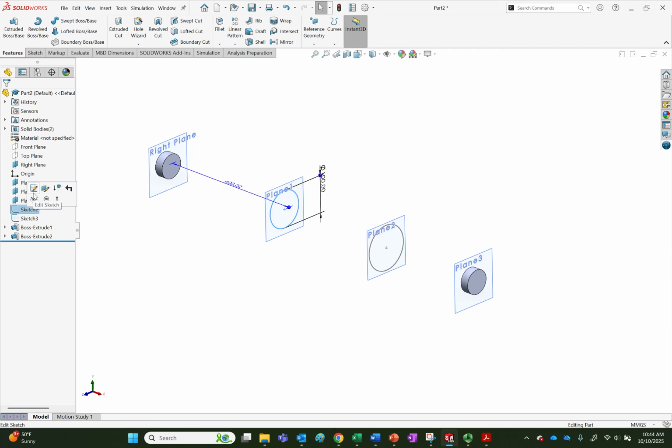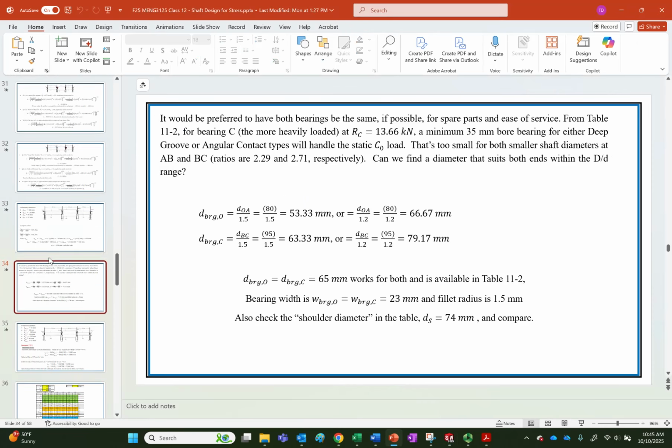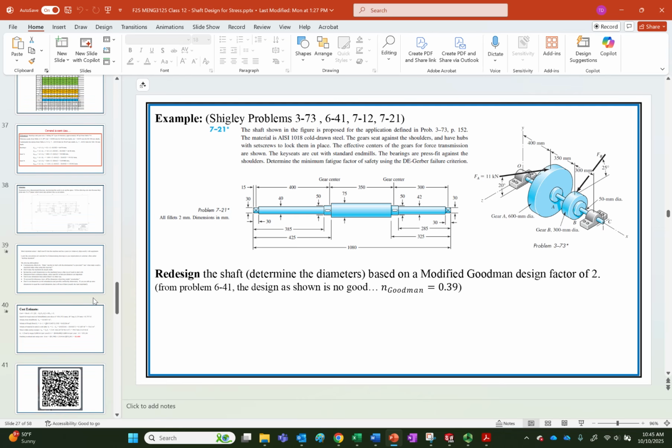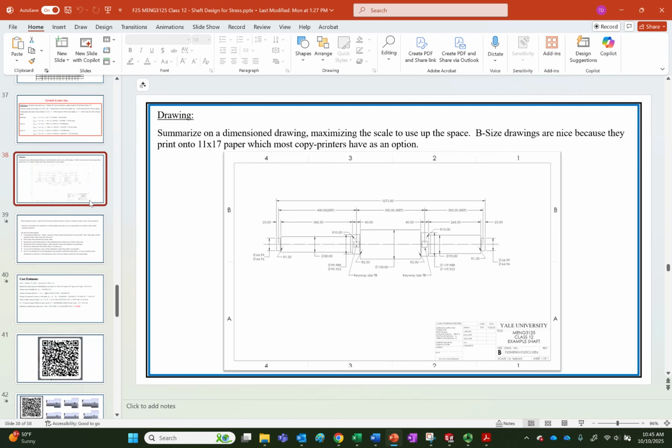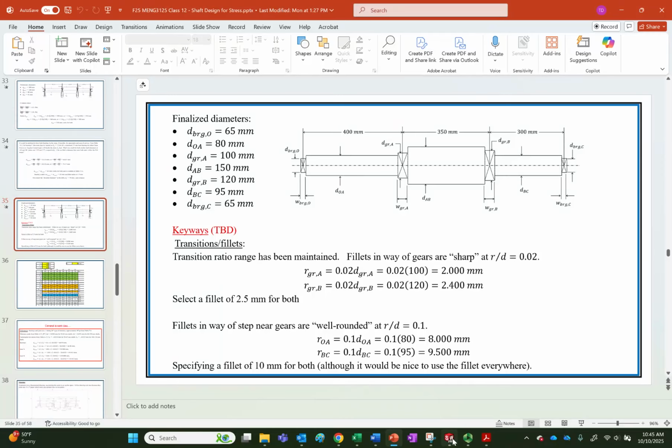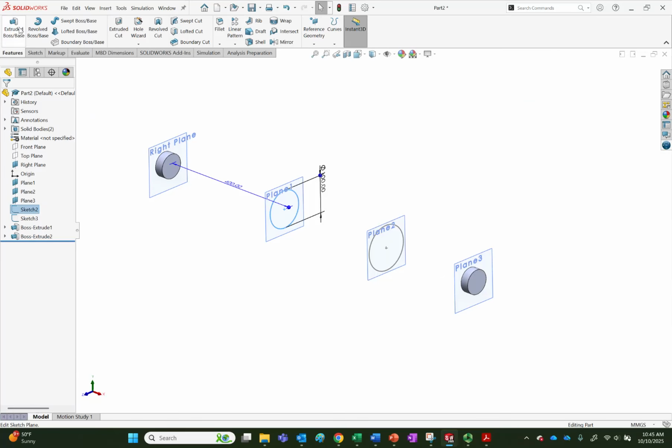All right, so we're going to go do sketch 2. Now, this should be 40 millimeters, right, for the gears. Because if you went to the very beginning here, the difference was 385 and 425. That was 40. And this is 325 and 285, so that was 40. And, of course, I already admitted I should have recognized that that's not exactly in the center. They don't tell you what it is, so that's why we're stuck here. That's why we're at where we're at, as it were. All right, so 40 into here.